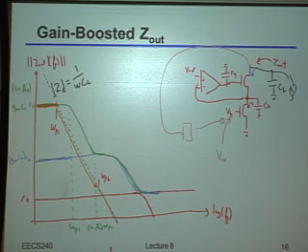All I'm doing is trying to make the DC gain higher and higher. And it turns out that oftentimes you need that DC gain just to make sure that you settle accurately enough. For example, if you want a 1 microvolt residual error off of, let's say, a 1 volt signal, that translates into something like a gain of 1,000,000. That's the only reason you play this trick. Good. Other questions on this?